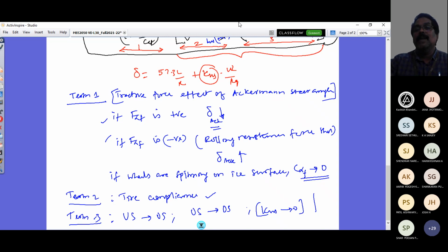When you drive a vehicle, suddenly you have to take a turn, you corner it, but what will happen? The vehicle goes unstable at a critical speed. That is what the unstable state is. So you will not have a steady yaw velocity. Instead, a drastic yaw acceleration can happen, and that would lead you to an unstable state.